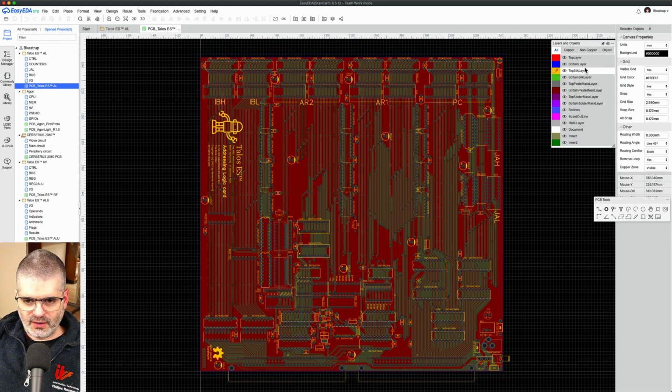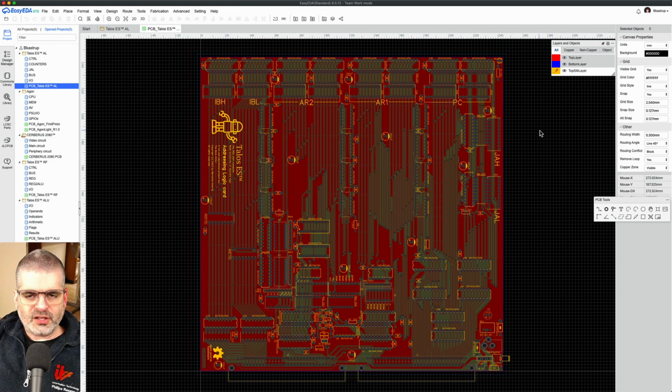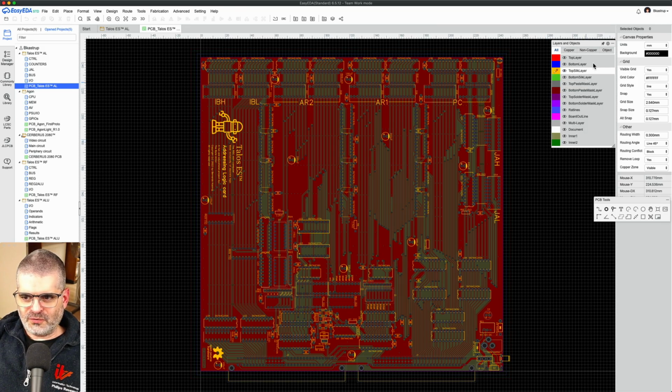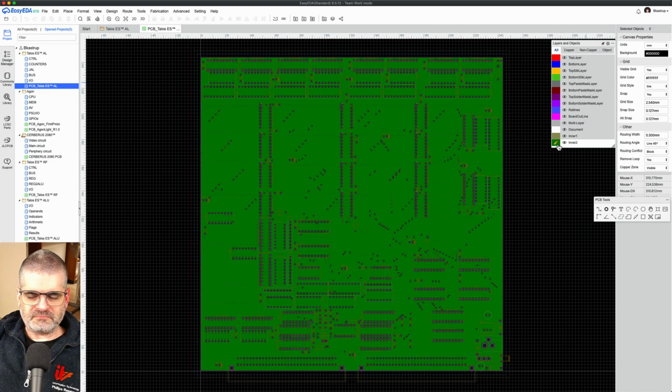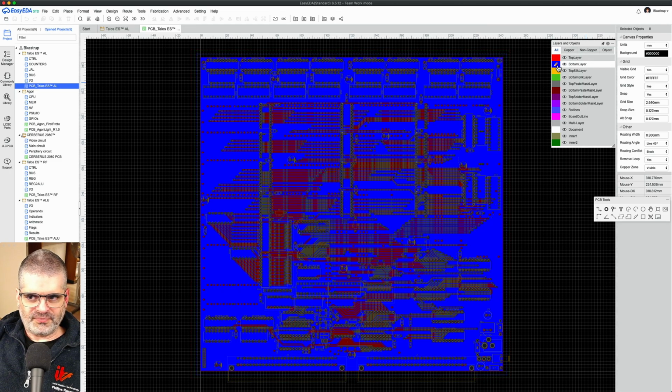As I mentioned to you, it has 4 layers, and the reason is it was becoming very tricky to route the power rail and the ground rail without using planes, and it was possible. It certainly is possible, but not with all the sandbagging and that I wanted to add. So I decided to add 2 inner layers. Inner 1 is a ground plane, and inner 2 is a VCC plane. And then all the actual signal lines are on the top layer or the bottom layer. Everything is routed there. So everything's still visible. You can still completely reverse engineer the board just by looking at it.